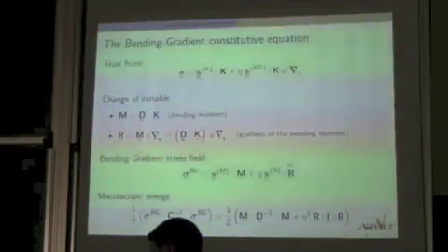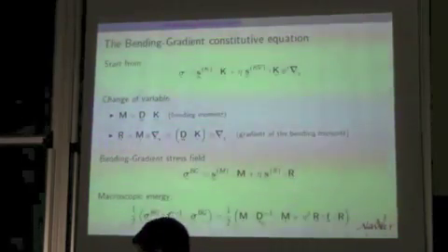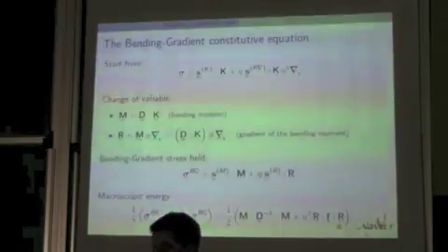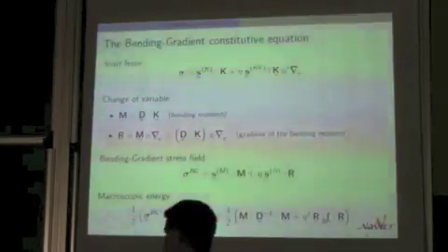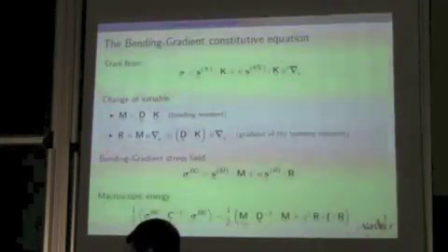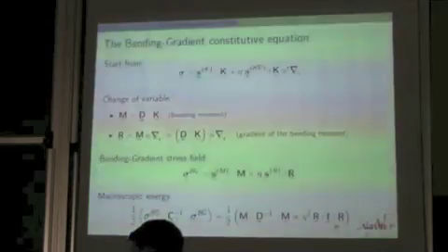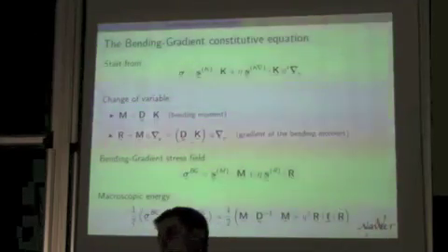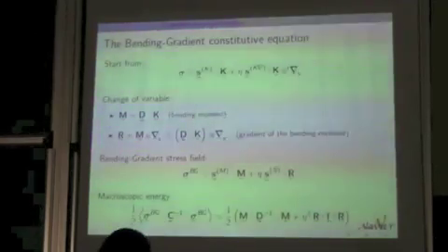So here, if I compute the energy of this integrating through the thickness, I get the bending compliance, minus 1, so the bending energy. And here something which looks nasty, but it is not. Something which is related to transverse shear effects. Okay? This tensor is just a 6-order tensor. So I like Samuel's notation about moustache, and I'm just a bit frowny today, but okay, just two frowns for a 6-order tensor. And this tensor is positive from this approach, but is not positive definite. Okay? It follows some symmetries. I won't go into details about that.